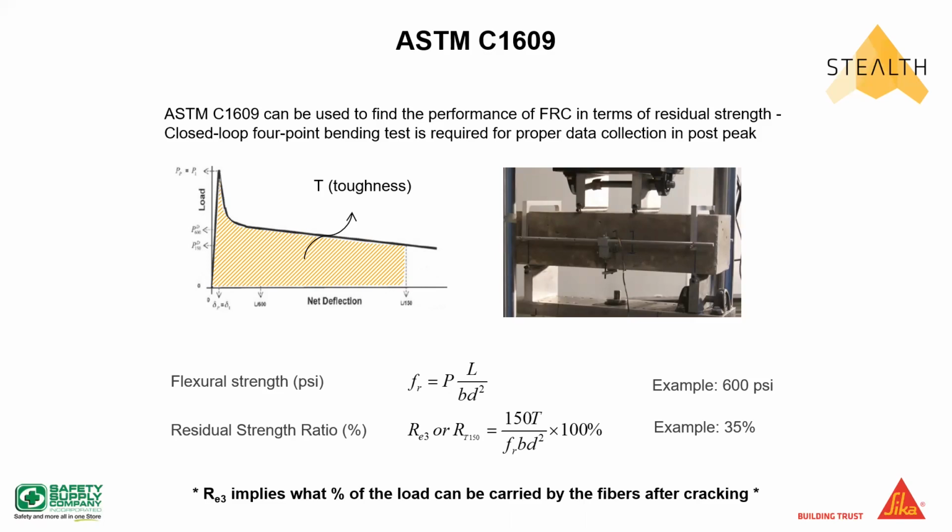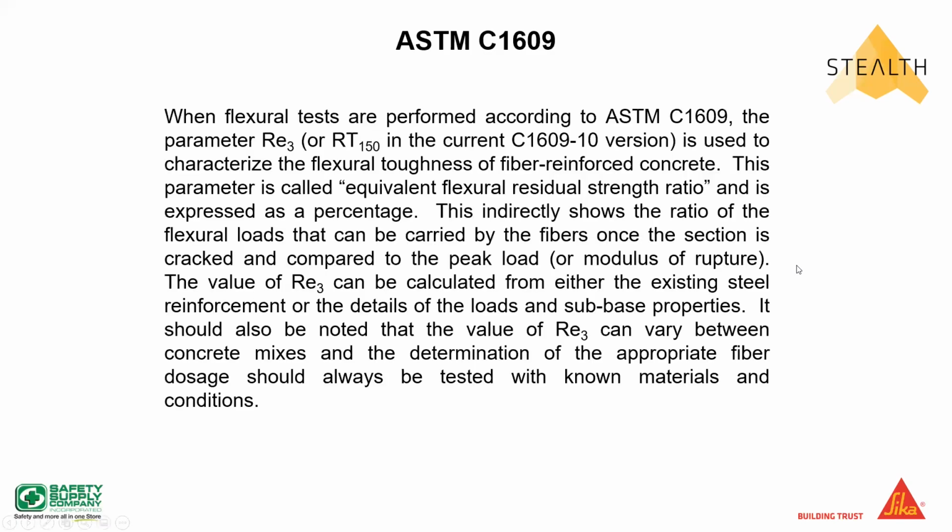Okay, so it deals with this guy right here, with RE3. Again, this is the spec the industry tends to use. It's been recognized for many years now, versus the other one that I'm getting ready to tell you about. The equivalent flexural residual strength ratio, all it is, again, is what's the load on the concrete when it reaches 3 millimeters of deflection versus where it cracked.